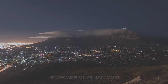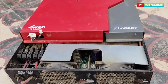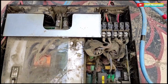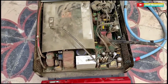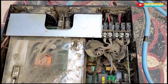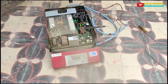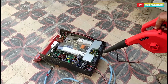Another big mistake people make is when they use a cheap inverter. Initially it costs less, but in the long run it ends up costing way more than the better designed inverter, which in some cases is only 30% more expensive. Cheap inverters have a poor design. Their circuit board is not sealed. Along with the air, the fan also brings in moisture and dust, which leads to the components of the circuit board malfunctioning.